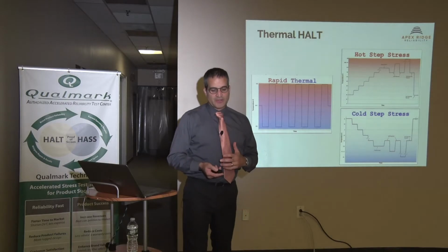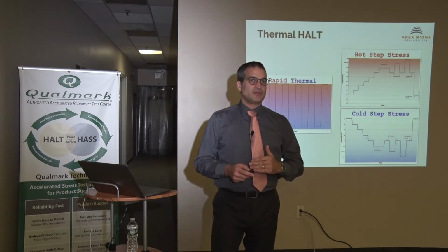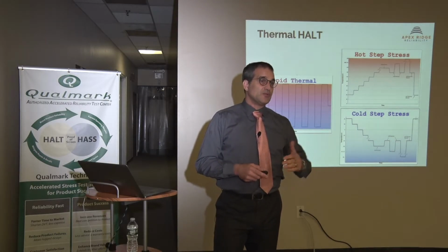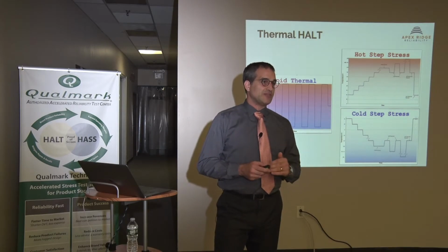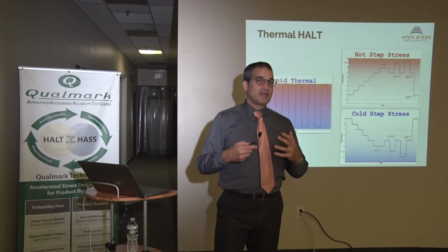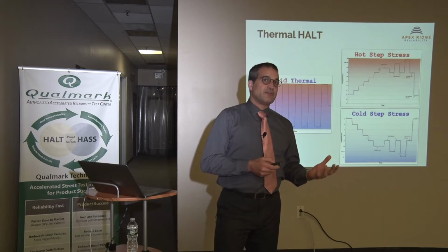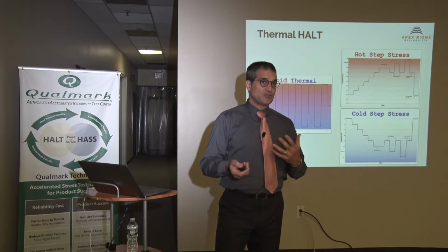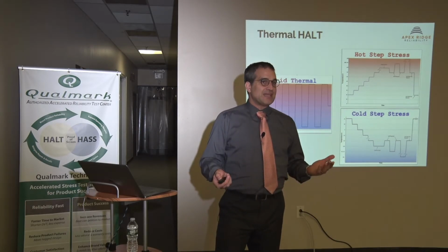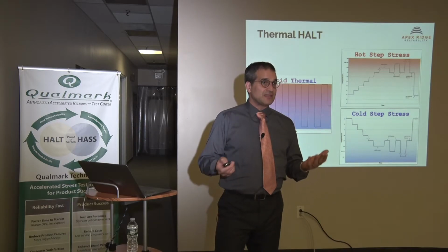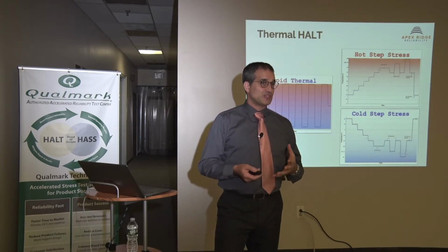The thermal. In a HALT chamber, we often have liquid nitrogen. You have to have liquid nitrogen be what drives the cold, and you have very high-power electrical heaters that drive the hot. Now, in a regular environmental chamber, you usually have compressors that drive hot and cold, but they cannot do it at the rate that's necessary to create the thermal expansion stresses.